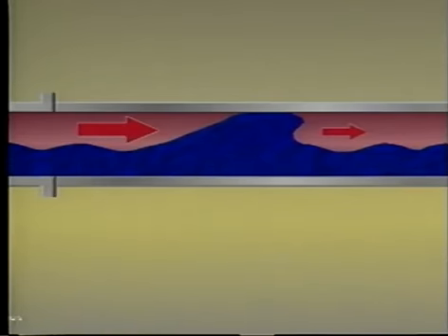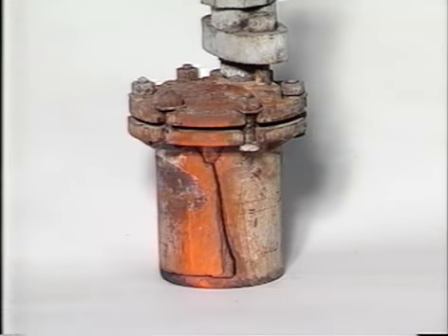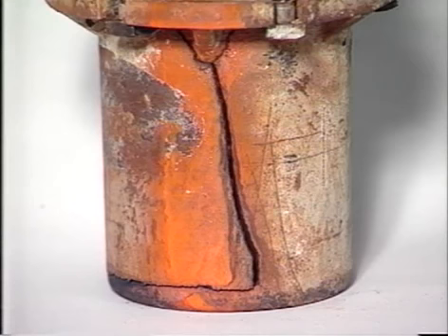Since the steam cannot flow through the condensate seal, pressure drops on the downstream side. The condensate seal now becomes a piston that is accelerated downstream by virtue of this pressure differential. As it is driven downstream, the piston picks up more liquid that is added to the existing mass of the slug, and velocity increases. This is differential shock. If the slug gains high enough momentum and is then required to change direction at a T or elbow or is stopped by a valve, great damage can be done.